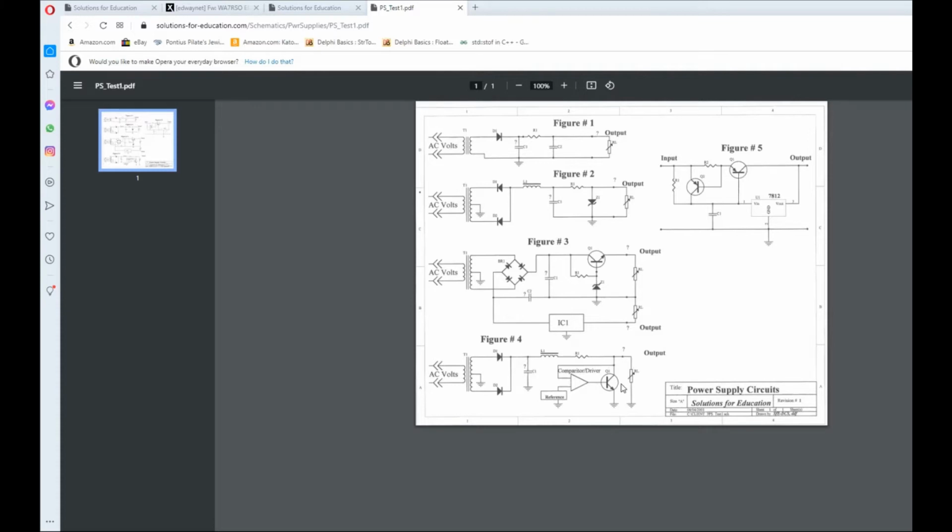As a shunt regulator, that means if this load suddenly goes to more resistance, drawing less current, this guy here has to draw more current to make up for the change in current here. The advantage of a shunt regulation system is that the load on the power supply source over here is constant, because this guy does a teeter-totter effect with the load.